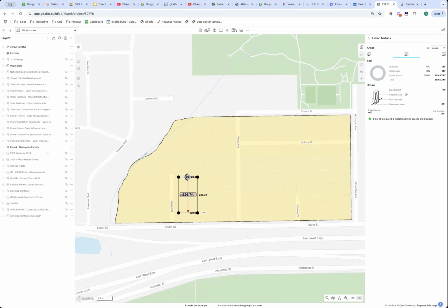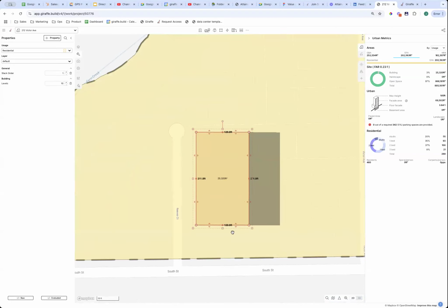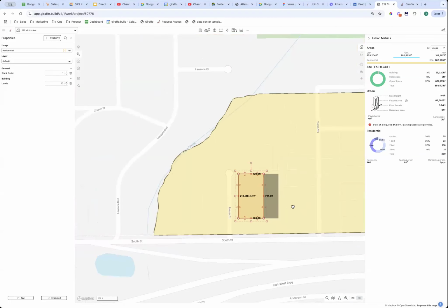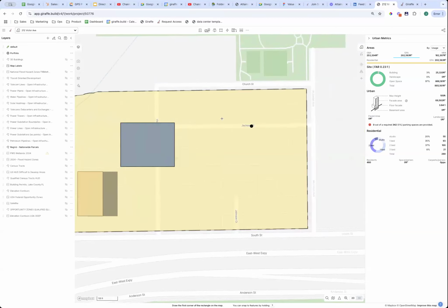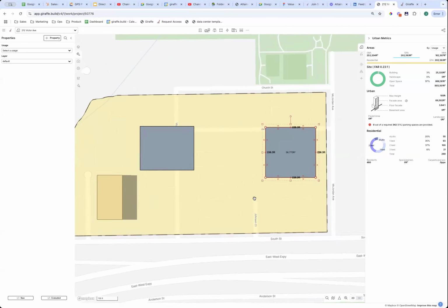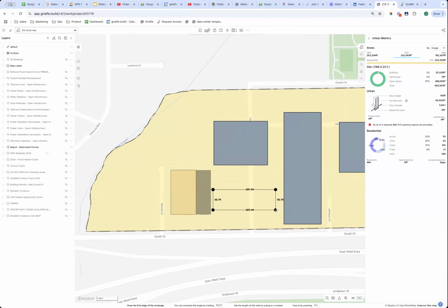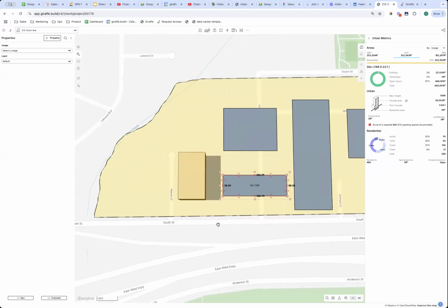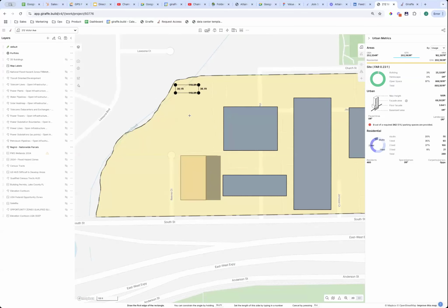And if I go down 211, let's say, then I can fix the depth of my rectangle. Okay, so go ahead and draw some rectangles. If you hit R on your keyboard, you can draw rectangles till kingdom come. And it's very fun. I like drawing rectangles. If you click and drag your rectangles, you can draw the length and breadth at the same time.